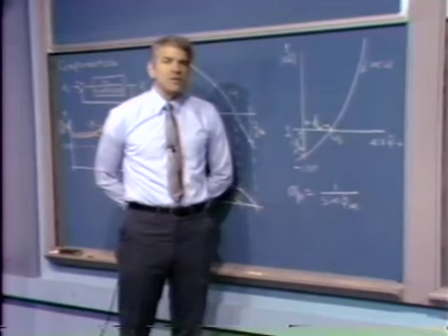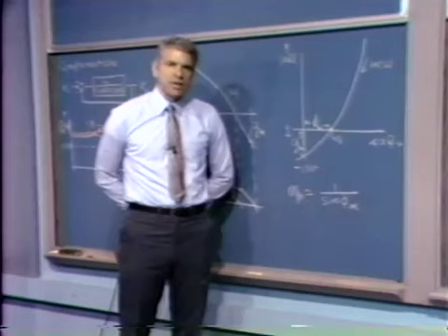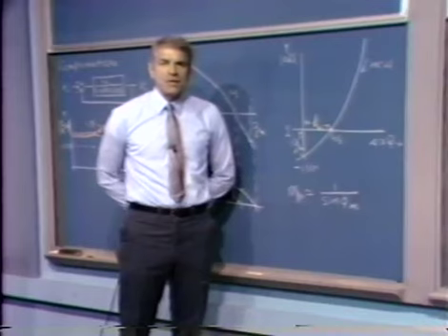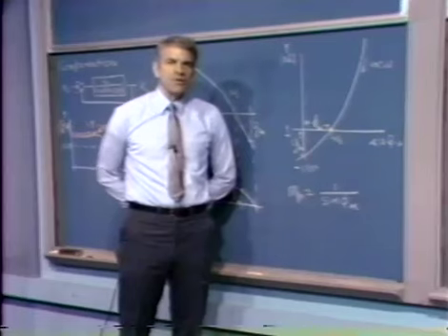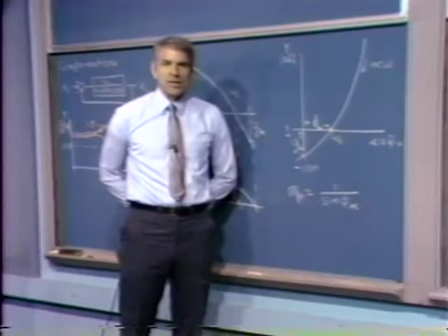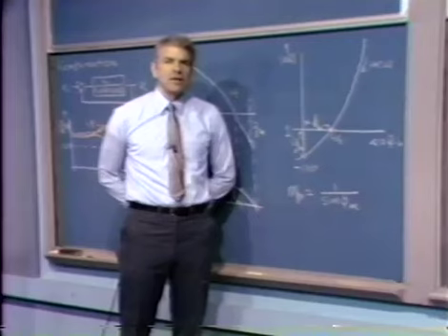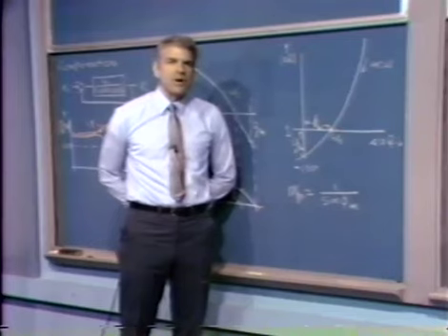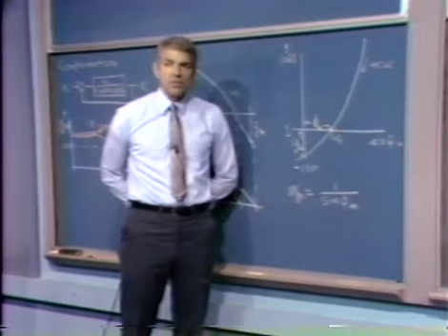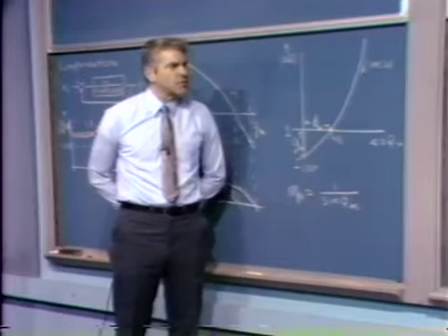And because it's so easy to do, I think almost all of the numerical work that one does with feedback systems really is based on these kinds of frequency domain concepts. We may use root locus as an aid to quickly seeing what's going on in the system and what might happen if we changed a zero location, or what might happen if we changed the location of a pole and that sort of thing. We can use root locus concepts to explore those issues very quickly. But when we want to get numerical results, when we'd like to go ahead and determine the correct value for certain system parameters, we almost invariably do that using Bode plot frequency domain kinds of techniques.